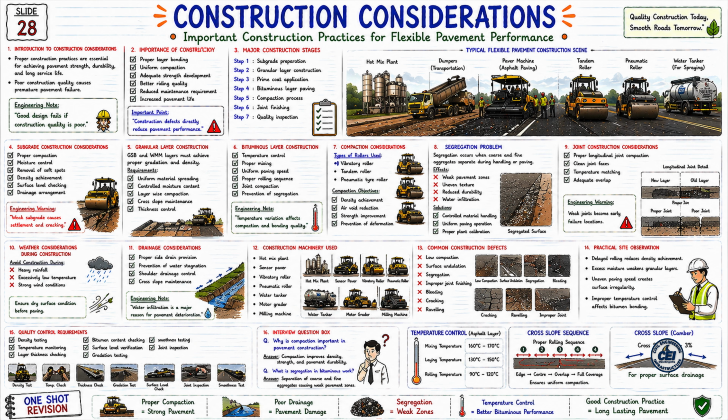Now let's look at the 16th topic. 16 Interview question box. Q. Why is compaction important in pavement construction? Answer. Compaction improves density, strength, and pavement durability. Q. What is segregation in bituminous work? Answer. Separation of coarse and fine aggregates causing weak pavement zones.